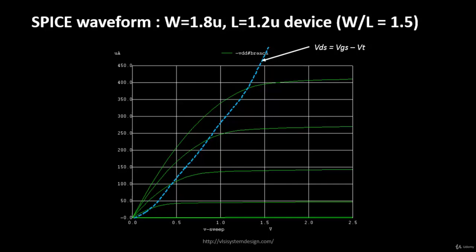Before that, let's try to understand this one. Let's say this is the curve. The reason I have drawn this curve at this point is that this area of the curve represents a completely different behavior of a MOSFET than this area. In this area, your drain current is linearly increasing. This is your drain current, this is your voltage. So drain current is a linear function of your drain to source voltage, and we had derived that some time back. Over here, your drain current is no more a linear function, but a function of 1 plus lambda VDS. That's your channel length modulation factor.